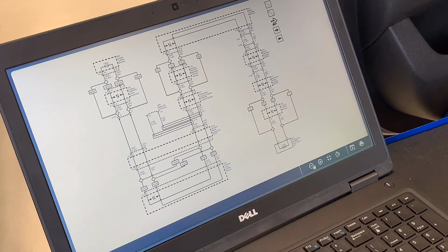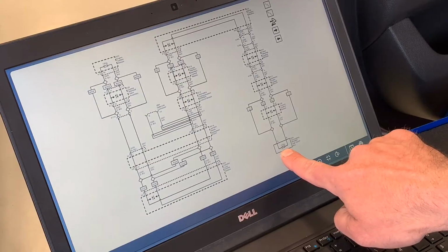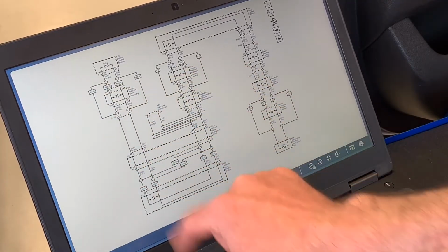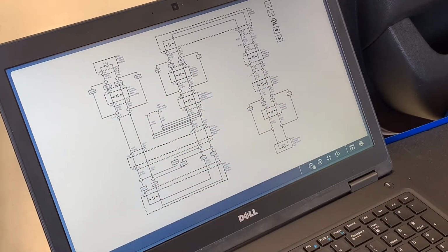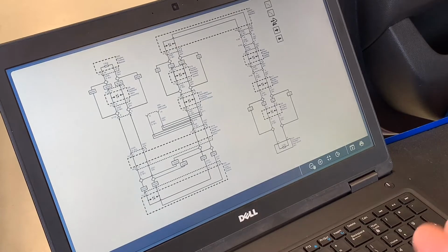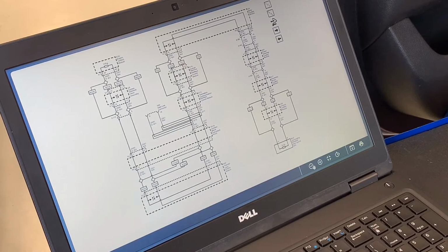One of the other unique things about CAN being that it's a 2-wire communication, those wires are actually tied together with a resistor at each end. We refer to those as the terminating resistors. And so I've got one down here, terminating resistor, high-speed bus, and one here at this other end. The low and the high then run in parallel through all the modules to connect them together. The good thing about this is that because they have a terminating resistor, if this wire was to get shorted to a power source, that resistor should help us save some modules. The other thing that is great from a diagnostic end is that if I've got 2 120 ohm resistors wired in parallel, I expect to see 60 ohms if I put my ohm meter across that.